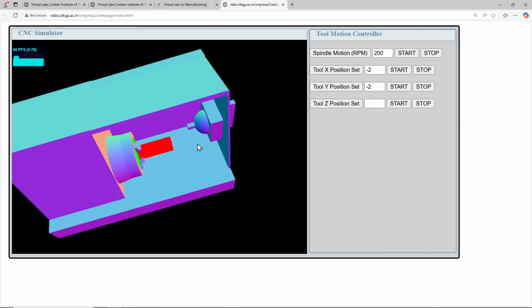For example, 0.1 mm inside, then it has to go 100 mm towards the left, and so on. So, these things we generally do. So, this is some general machine setup. Let me just try to touch it. I will touch it from this direction.